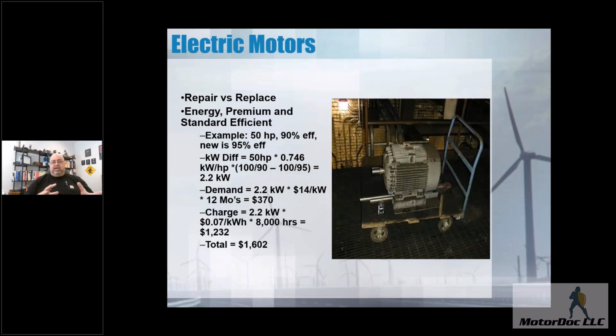And most of the time on older motors, say if it's an old T-frame, just a straight motor or a U-frame motor, you're only going to get 2 or 3 rewinds out of it before it really becomes more of a heater than anything else. If you want to get an idea, you'll see just with a plain clamp-on ammeter, you'll see an increase in current for the exact same load before and after.